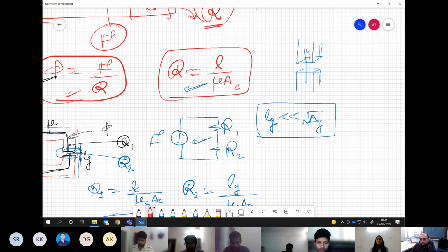Similar to electrical machines, we have a stator and rotor where one part is stationary, another is moving. So of course, air gap is required. Now, that air gap length, when we are deciding, we need to ensure that it should not be too large that the flux lines start jumping through air through a different path.